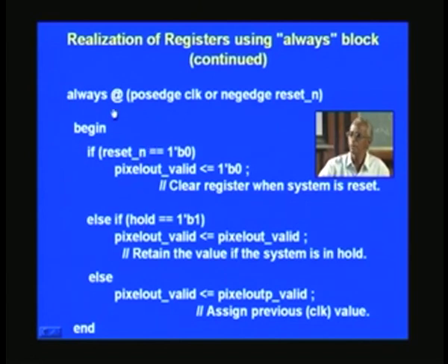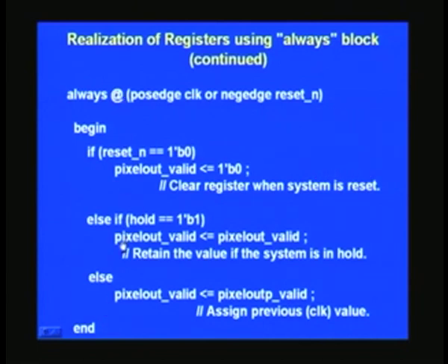And the second thing is, you are not bogged down by so many details, I mean so many signals. If you don't stick to this, what I have observed over the years is a number of designers putting hundreds of variables in one always block, and the result will be chaos, and you will get drowned in the myriad of signals, so avoid that. You can always put any number of always blocks, and you can rest assured that each of these always blocks will be functioning concurrently. So there is no need for you to put everything together and not make the system work, and that will be a frustrating experience, especially for a beginner.